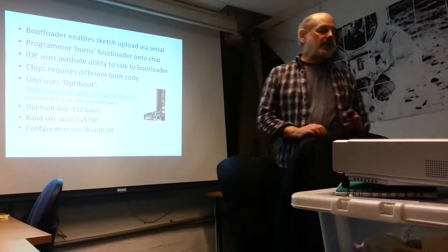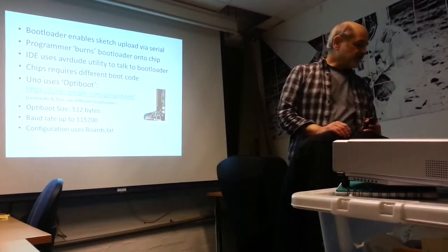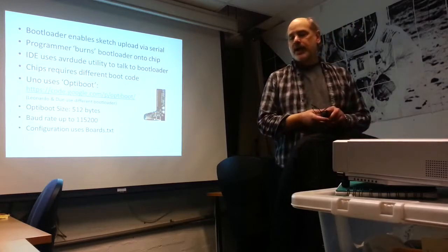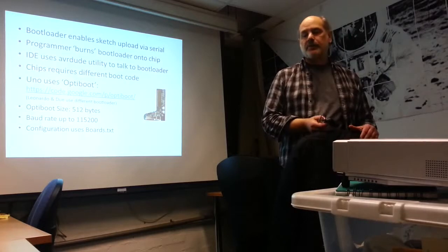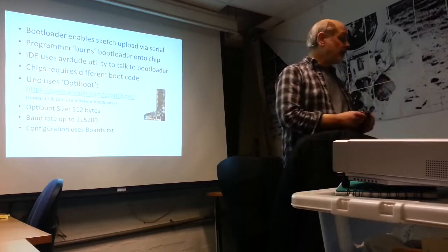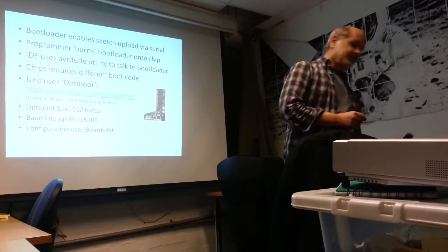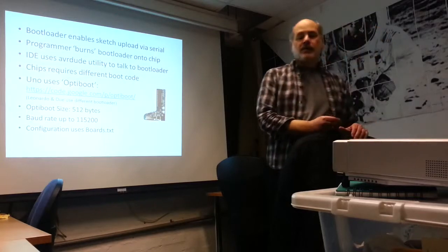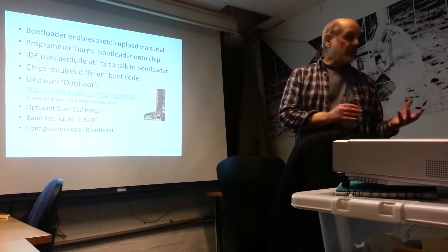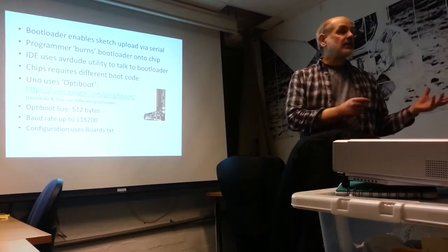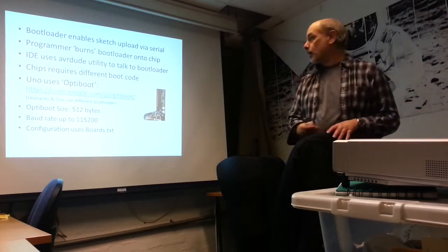So the bootloader enables the sketch to upload via the serial port. The way the bootloader gets onto the chip is, obviously, it's manufactured in when you buy the Arduino board. But if you buy a raw CPU, it will not have the Arduino bootloader on it, and therefore you can't upload a sketch until you put one on.